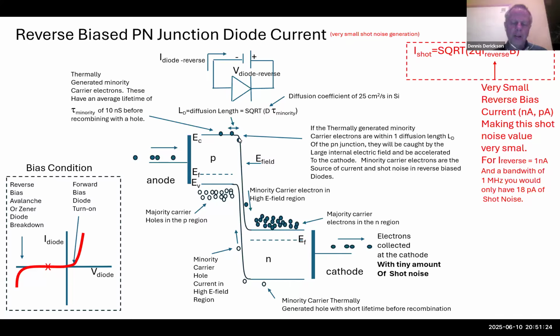And that kind of current is called drift current. When you're moving an electron through an electric field, we call that drift current. So it diffuses over here from the edge, starts on the electric field, and then a drift current forms. And the electron, as it goes down this potential barrier, will convert lots of potential energy into a tremendous amount of kinetic energy right here. And eventually it will fall down and join the big population of electrons right here.